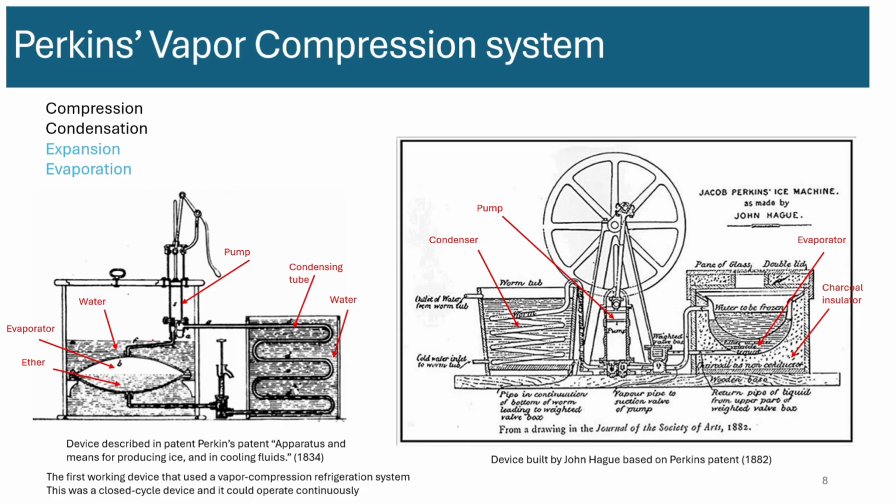All right, and once the vaporized ether is pulled, it is compressed by the next stroke of the pump, and then it passes to the condensing system where it exchanges heat with the water and cools down and becomes a liquid again. And at that high pressure, it comes back here, and this valve opens, goes back in here as a liquid, and then evaporates again. Okay, so that creates a full closed cycle. And you can see that there's compression, condensation, expansion, and evaporation.